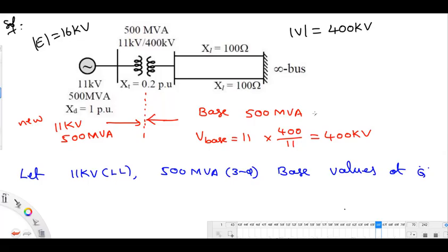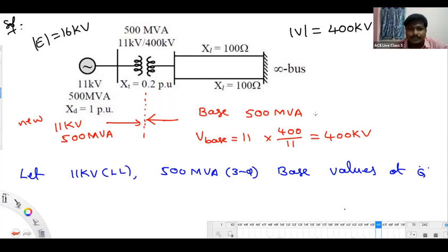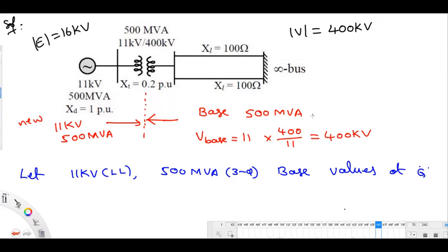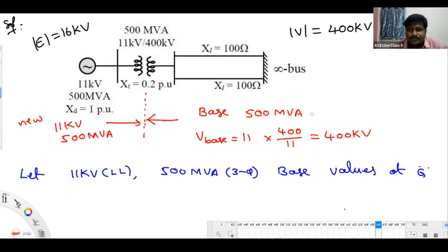I asked them and they told me it is to supply reactive power, so they keep the reactor in the substation. What's the rating of that substation? 400 kV. Then it's okay. It's a shunt reactor. Shunt or series?